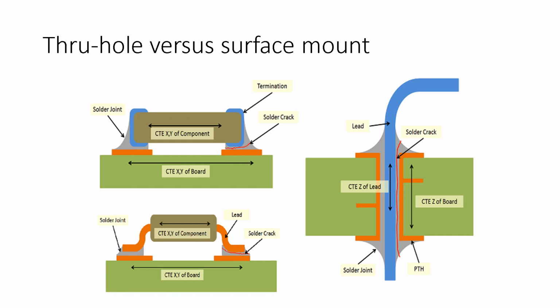On the very right-hand side, you see a through-hole one. So you can see this long leg, this long lead going the entire way through the circuit board, and solder is just being essentially pumped the whole way in between those. And so this could be going through a via of some kind in the circuit board, or some other designation that we have designed into the circuit board to hold it. But through holes have a very, very high amount of contact and mechanical contact between the lead and the circuit board itself,